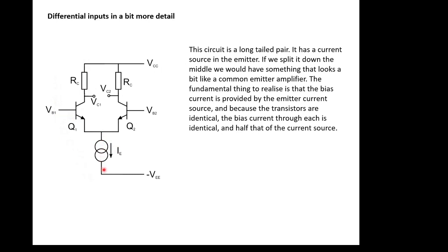And this is okay, but if you only had a single transistor amplifier, so if we got rid of this part over here and only had this, it would never amplify anything, because the current through it would always be constant, because it's been fixed by this current source. So that's no good to us, which is why we have to have another transistor opposite, to give us a chance of actually varying the currents through these transistors. They're still fixed by the current here. So this current down here plus this current down here must always add up to this current here, which never changes. So this is constant.